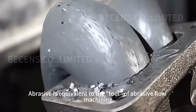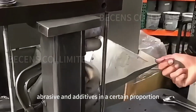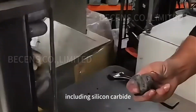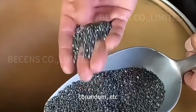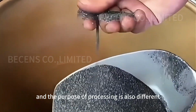Abrasive is equivalent to the tool of abrasive flow machining, which is composed of carriers, abrasives, and additives in a certain proportion. The hardness of the abrasive is relatively high, including silicon carbide, aluminum oxide, corundum, etc. The viscosity of the abrasive they form is different, and the purpose of processing is also different.